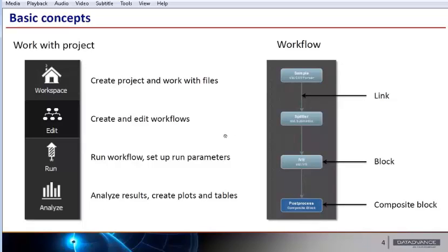For those who attend our webinar for the first time, let me briefly say how the user usually works with pSeven. The engineering problem is described with a so-called workflow in pSeven. The workflow consists of blocks. For example, there is a block of integration with Creo, a block for optimization, a cycle block, a condition block, etc. Blocks may receive data and write data to their input and output ports. For example, a simple calculator block that multiplies two numbers will have two input ports and one output port, where it will write the result, and where this result will go further depends on the links between blocks. The link is a data channel that connects blocks and sets the sequence of their execution.